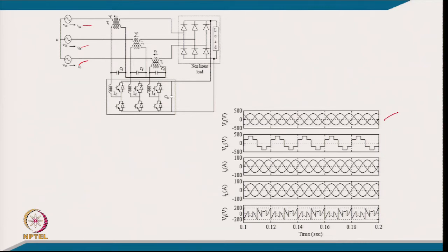If we consider the 3 phase supply voltage sinusoidal and balanced, then this is the voltage that typically comes here after the injection of this voltage by the series active filter. If we inject this voltage, the difference of this voltage automatically will be of this nature, and if we really enforce such a condition, then we get the supply current balanced, sinusoidal and in phase with the supply voltage, having a unity power factor. And of course, whatever the supply current is, it is the input of the AC side of your load current, because they are connected in series.